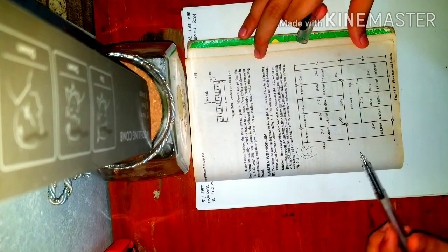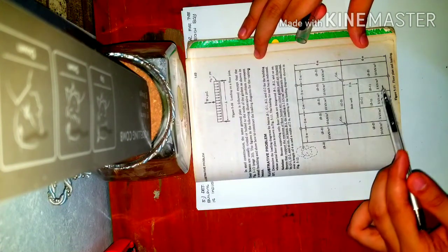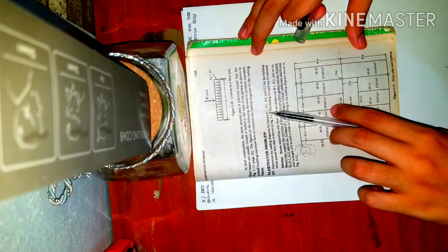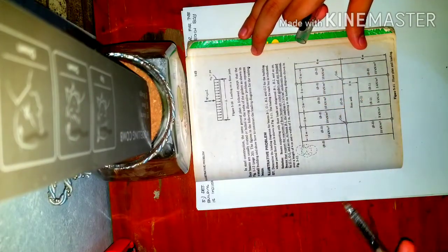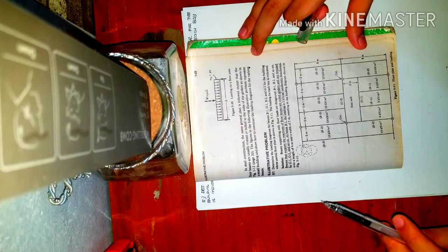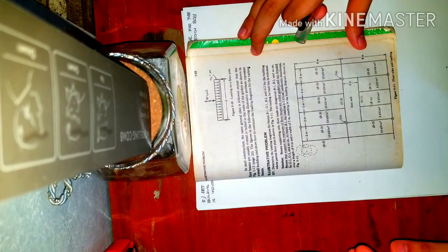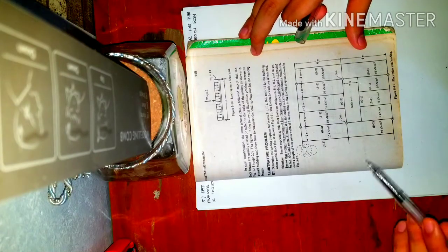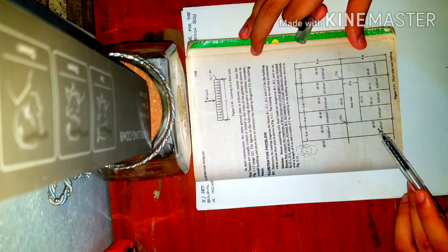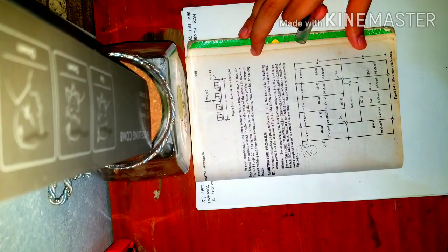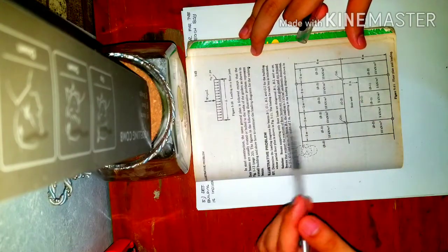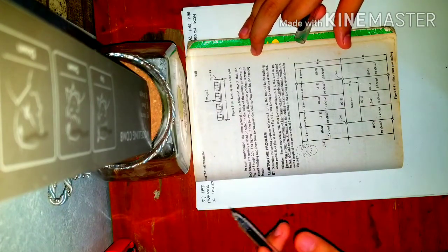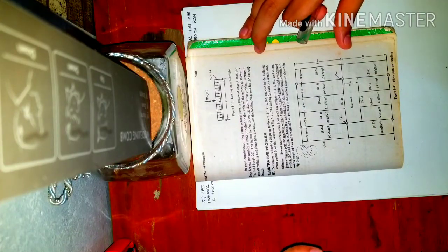So the first thing we need to do is to determine the loading on the beams. The problem asks us to determine the loading diagrams for the beams B1, B2, B3, and for the girders G1 and G2. From that, many things can happen. Once you have the beam, for example, I can give you the cross-section size of the beam and ask you to compute the flexural stress, horizontal shearing stress, and so on. So from this problem, many problems can be made. Don't be afraid, that's why we discuss how to attack this problem.